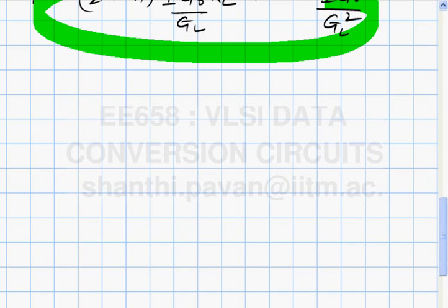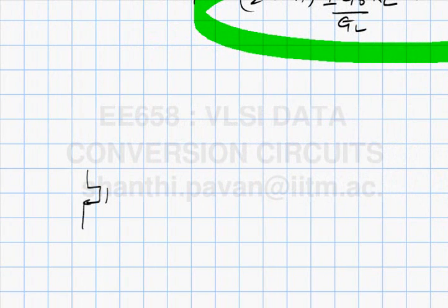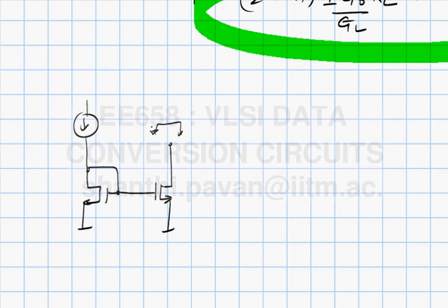So, the best way of enhancing output impedance is what? This is your original current source. The output impedance here is not good enough. So, what will you do? You take this current source and pass it through a current controlled current source. A current controlled current source is a contraption which takes in a lousy current and makes it look like a great one. A current controlled current source ideally has 0 input impedance and infinite output impedance, correct?